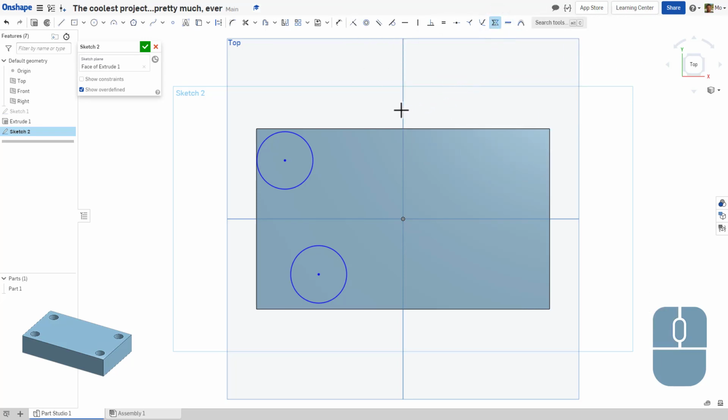If we click on this, what do we need? We can either click on both of the outsides of the circles, or both of the insides of the circles. Let's click on the insides, 1 and 2. But then what else do we need? Well, we need to select the line that divides them. So when we click here, on the front edge, pop, you'll notice that that circle has moved to mirror itself across this line. Very cool.